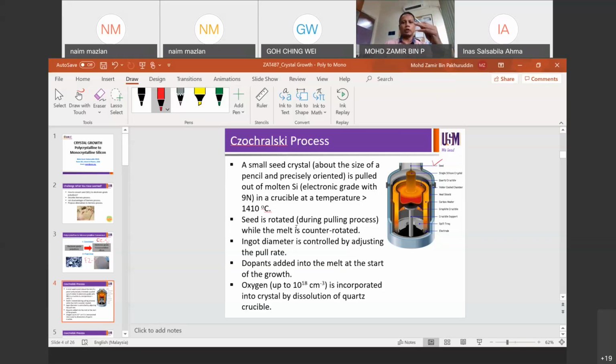We've learned last time in intrinsics that you can go undoped intrinsic, lightly doped, moderately doped, or heavily doped, according to what you want to achieve in your materials or devices. If you want to grow N-type, then you need to incorporate phosphorus into the melt and do the very same pull and control process. Then we're going to end up with N-type silicon.